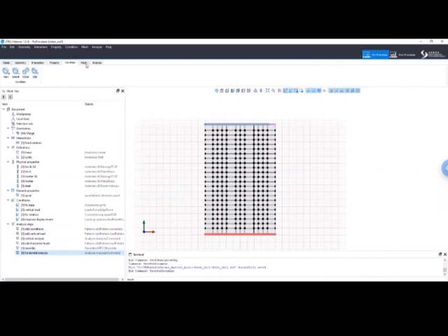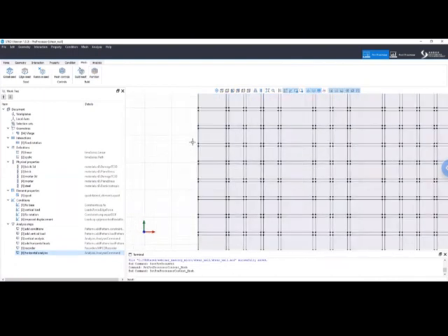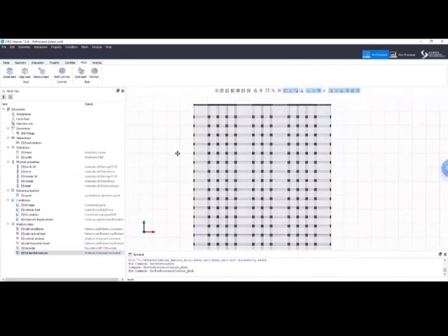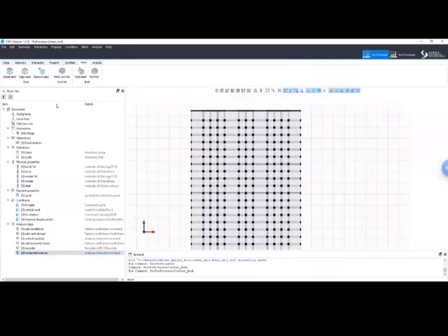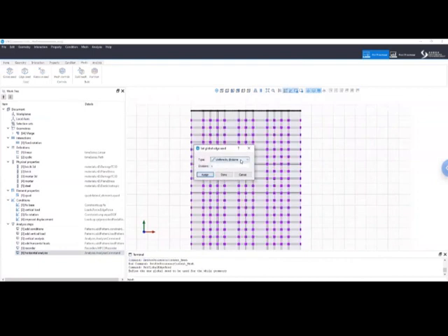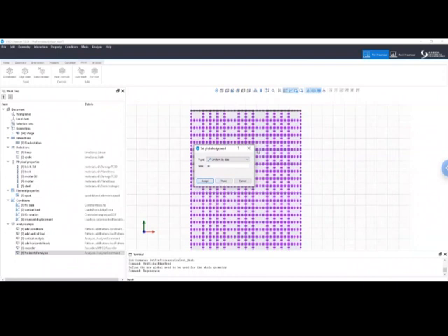Now, the last thing that we need to do is to create a mesh. Here, the best thing would be to use a mesh size with the same height of the mortar joint thickness. But here we want to make things faster, and the results will be good anyway. So we're going to choose a global seed, uniform by size of 30 millimeters. Let's press assign. As you can see, this one will be the dimension.